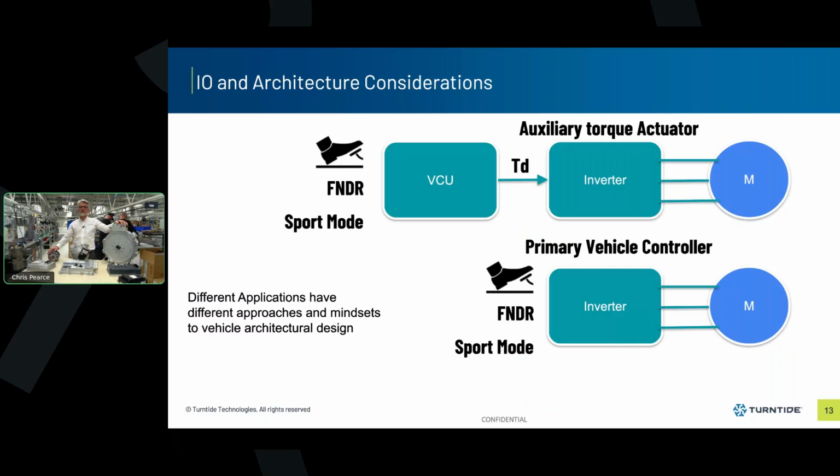You are likely to be taking in switches from a user or an automated system over CAN probably, or via switches, potentiometers, and other input devices. That could be done into a remote unit and sent to us as a torque demand, or the torque command can be calculated on board. There are also considerations regarding isolation of the system and how your I/O switches in terms of either to 12 volts or battery voltage, and these kind of architectural constraints that have to be considered when selecting your inverter.